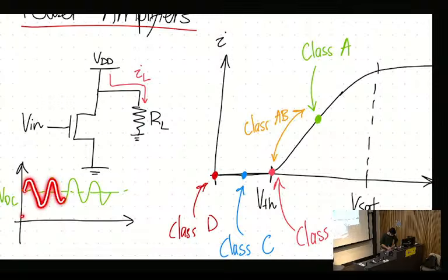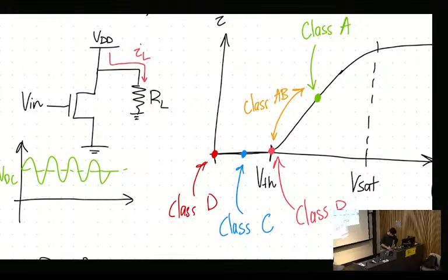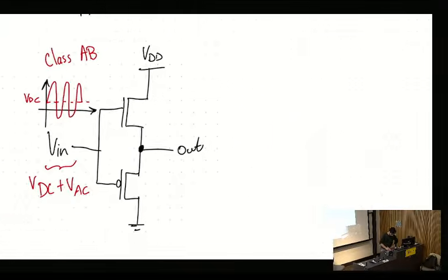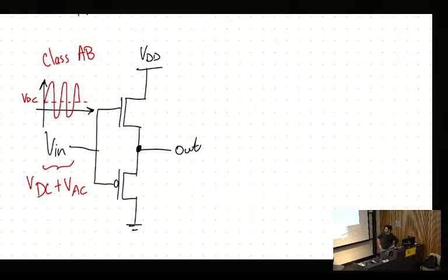So we're always above the threshold voltage, which means this amplifier is always swinging from more on to less on, so we always have positive voltage, whereas in this case we have both positive and negative swing, giving us more power. Yes, exactly. I definitely do recommend going through the maths because it explicitly shows what that means. Any other questions on that?